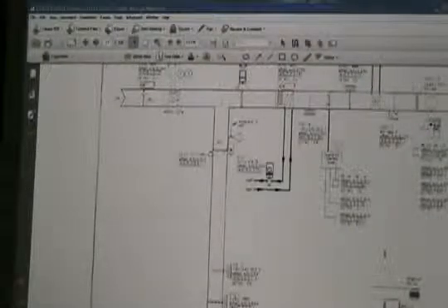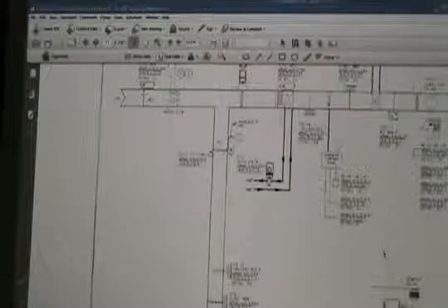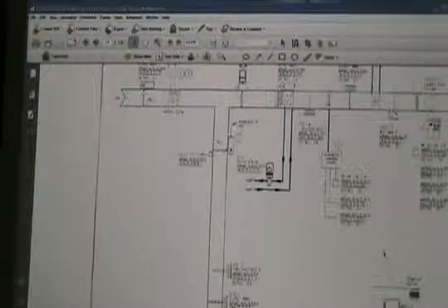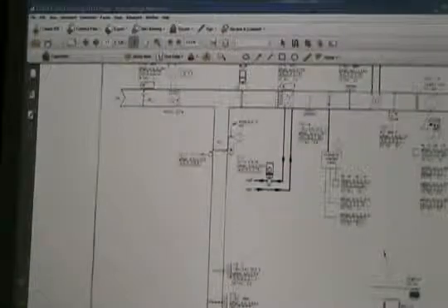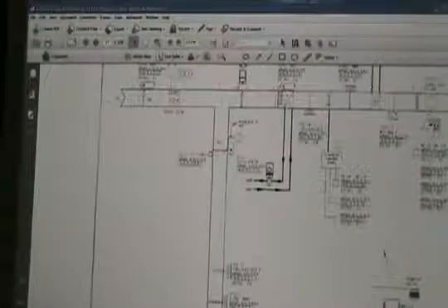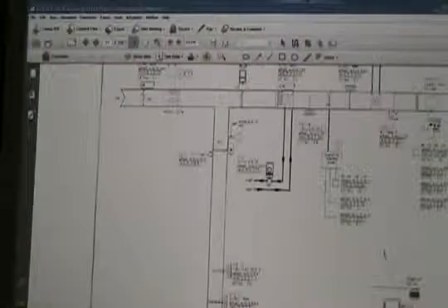He doesn't say anything. If we open that damper, again, we're mixing air, so it's summertime, we're mixing air. Let's say this is 72 degrees, and that's 98 degrees. We could have a mixed air temperature here of a higher set point than what the intended coil could handle. So there's nothing in here to reverse that situation if we can't maintain 55 degrees out here.